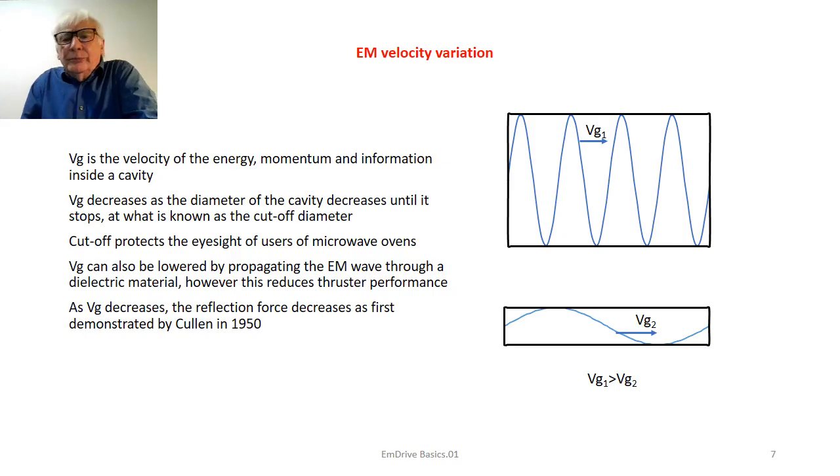A problem with this is that if you do use a dielectric material, and we have used it in experimental thrusters, unfortunately the losses inside the dielectric material are much more than the losses for an air-filled or a vacuum-filled cavity, and indeed we've found it becomes impractical to use a dielectric filling for a practical EmDrive thruster.